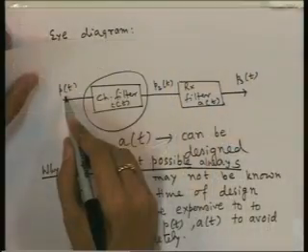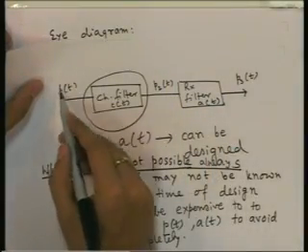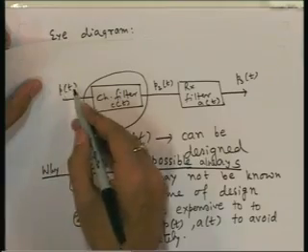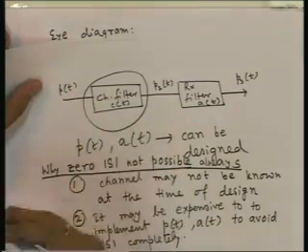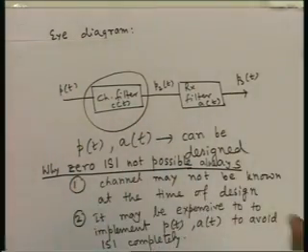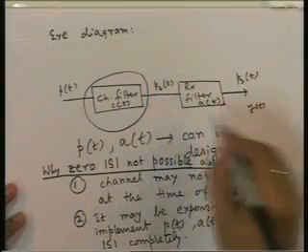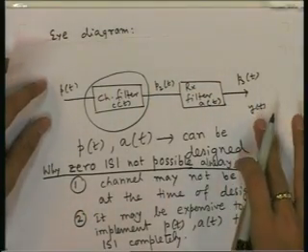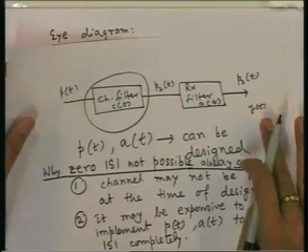So, we will not transmit only p(t), we will transmit the summation a_i p(t minus iT), that summation, that is the many symbols. We will be transmitting symbol after symbol, and we will receive some signal here. So, that is y(t). Noise will also be there. Now, we simply try to see y(t) on an oscilloscope with symbol timing as trigger.